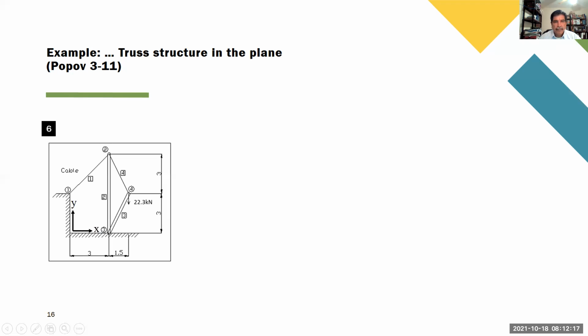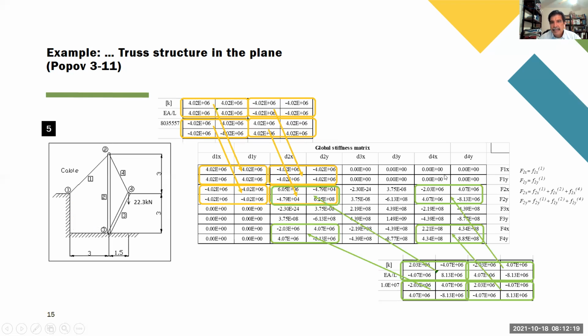What else? Okay, remember, this stiffness matrix is the global stiffness matrix. Right now, for example, I have 4 joints, and this is 8 by 8. Okay, because every joint has 2 degrees of freedom. Okay, now, if you calculate the determinant of this, there is a question from somebody?